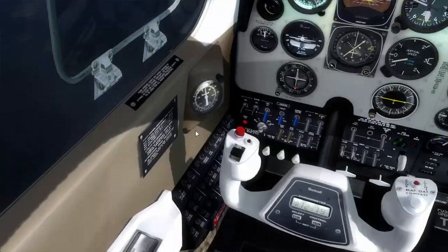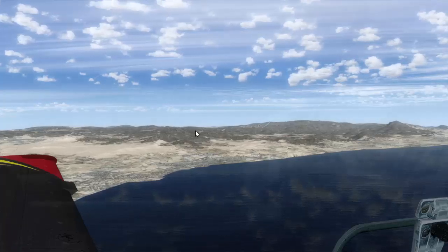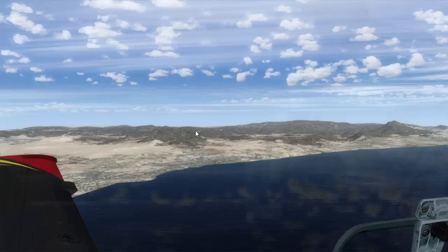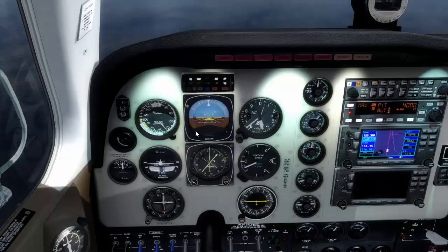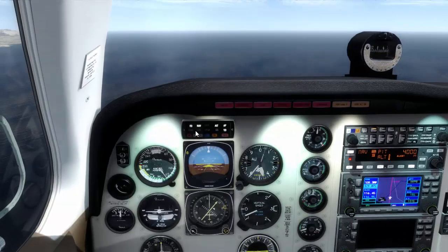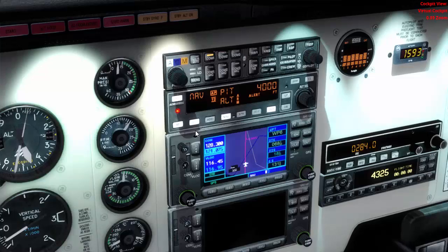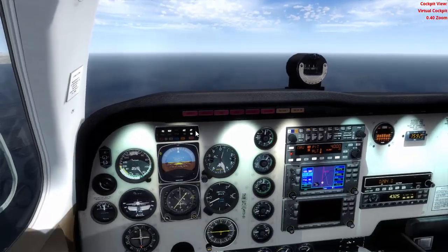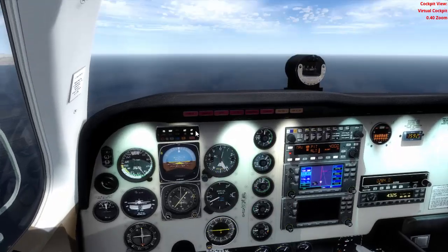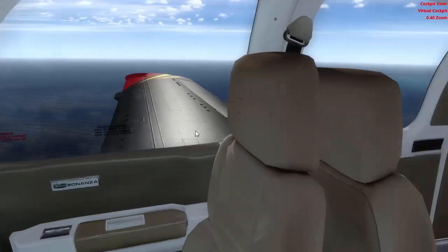and that means exactly that you will need to control other things in your flight, like the vertical component, because the aircraft can get aligned with the radial, and we could have a VOR DME station at the airport, close to the runway, and we are following a radial from that VOR station. But that will only align our aircraft more or less to the runway, because we will have a radial that is crossing in front of our runway, and we will be able to align more or less, okay,